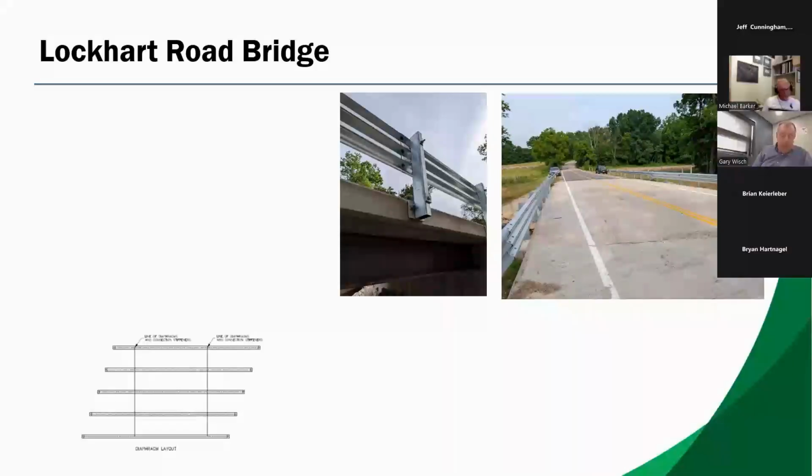Then the only other fabrication operation that had to take place was to camber the beams to account for the dead load deflection so that the beam would properly conform to the roadway grade after the slab was poured. So for us, and I know we're running short on time, but for us, these were really simple and easy to fabricate beams, and we were able to compete with concrete.